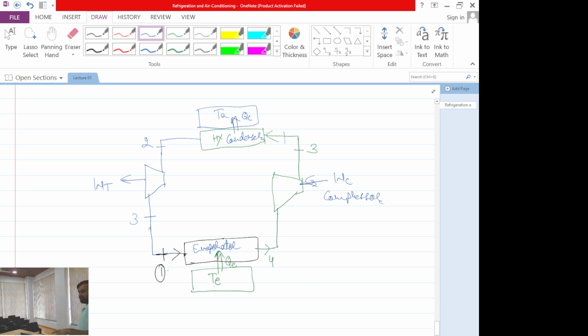Okay, earlier I had the boiler at the top and the condenser below. Now the evaporator is at the bottom and the condenser at the top, and the pump and turbine are swapped. So again I have the same TS diagram, but the processes are taking place in reverse.